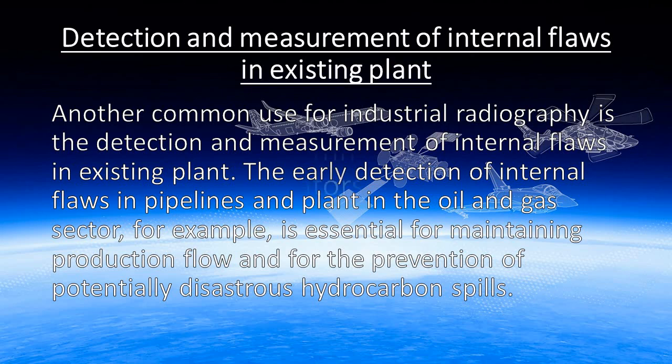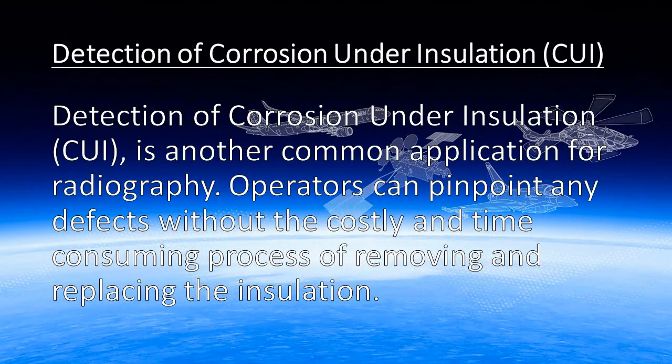That is important. Detection of corrosion under insulation, which is called CUI, is another common application for radiography. Operators can pinpoint any defect without the costly and time-consuming process of removing and replacing the insulation.